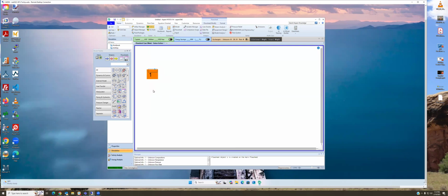Now let's anticipate something. We're probably not going to consume all of the acetone in our reactor. And so somewhere down the line, we're going to be purifying an acetone recycle stream and then recombine that with our feed stream going into our first reactor. And a good way to help the simulator do that kind of a calculation is to add a unit called a mixer. Now, we're not specifying what this looks like. It might be a couple of pipes just teed together. It might be a tank or something else. But it helps the simulator do the calculations if you include this when you're eventually going to be combining streams.